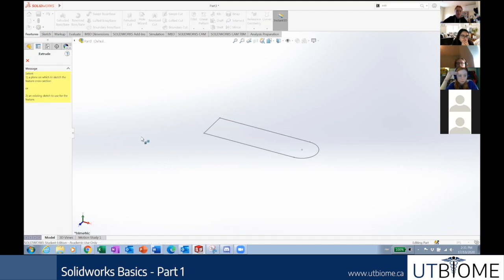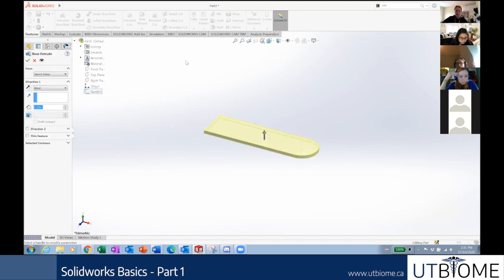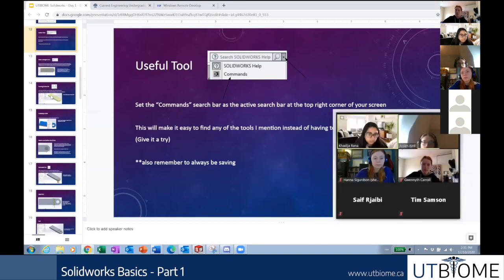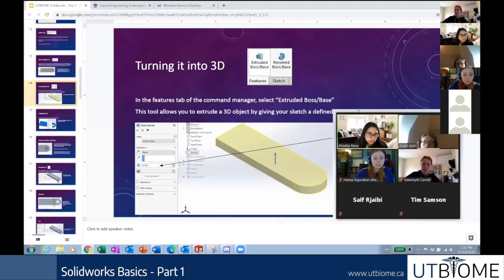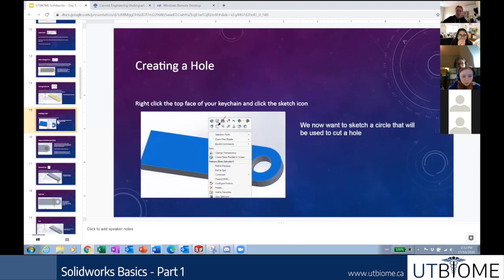There's nothing special happening here. There's no preview. So I believe I can just click it. I can. You could possibly just click your sketch, or if we're really struggling because we're doing a really intellectual part, you open up this little menu here that's closed. This shows you all the features and your sketches, your planes and everything. And you just would go all the way down to sketch 1 and we're back at the same screen for extruding. So let's see what the dimensions are for this extrude. Okay, so we are going to extrude 0.25 inches.